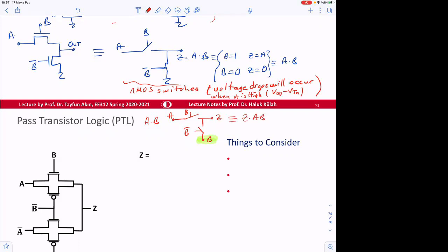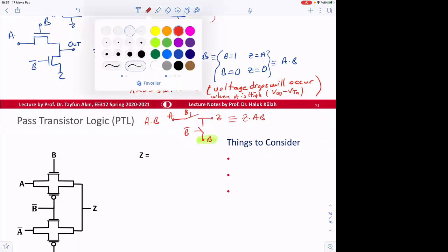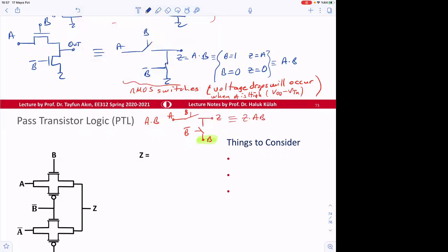And the first thing, which is very important, is never leave the output port floating. Output port floating. Okay, so for all cases, you have to make sure of this.